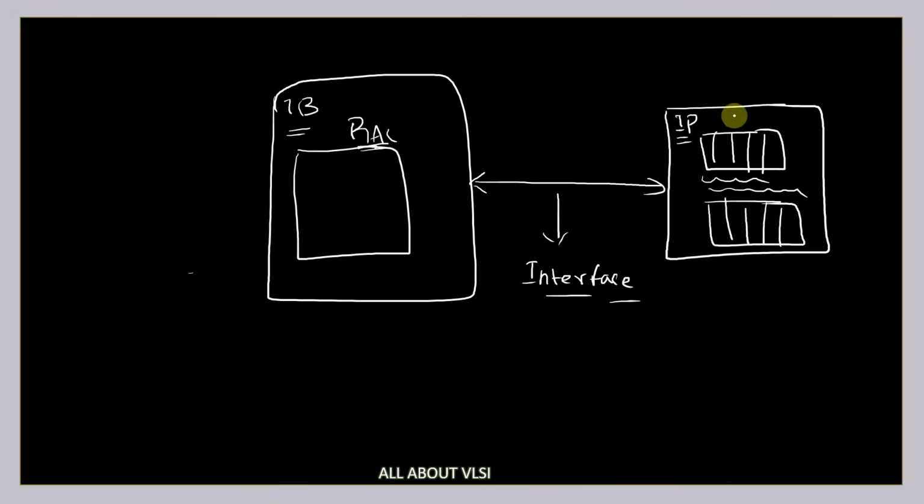Let's say I have two registers. Using my RAL model, I replicate these exact two registers inside the model, and whatever values I update inside the design registers will be replicated inside my RAL model also. This is how my RAL model keeps track of whatever internal registers are being configured inside my IP in my test bench.